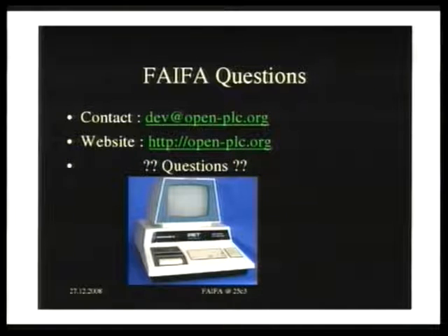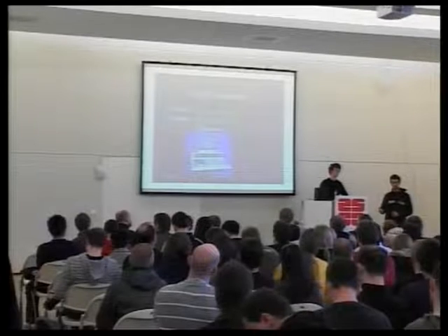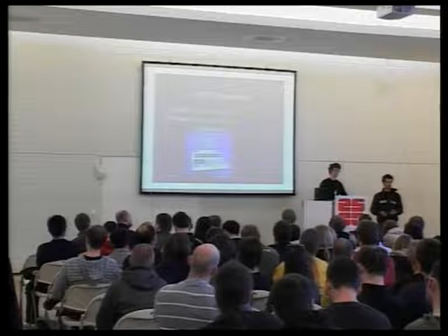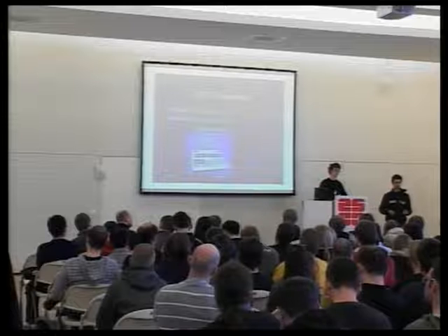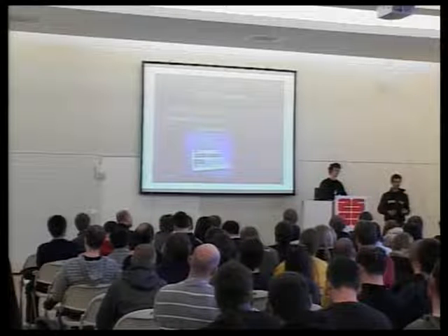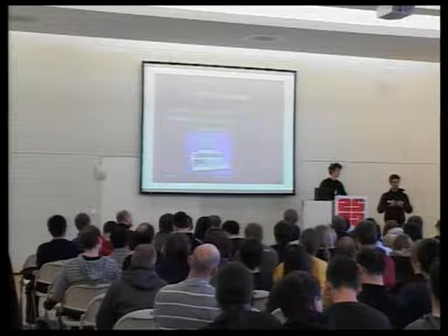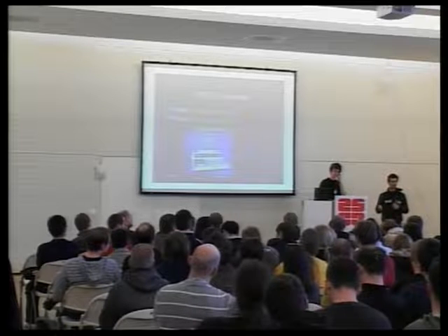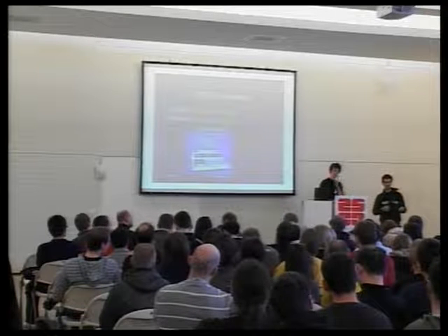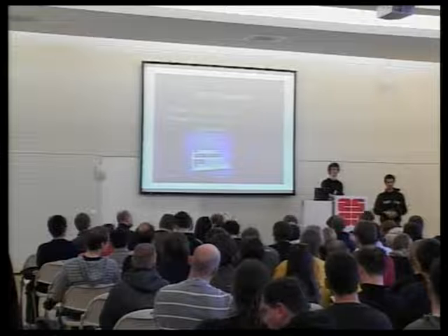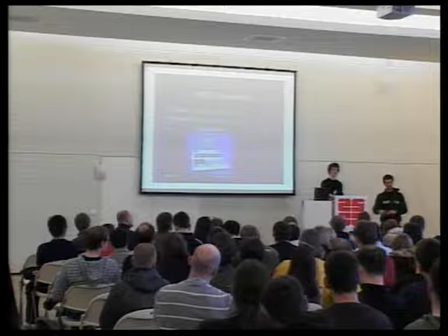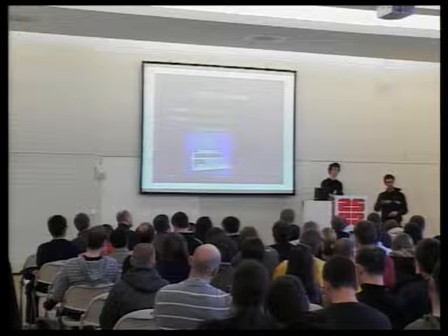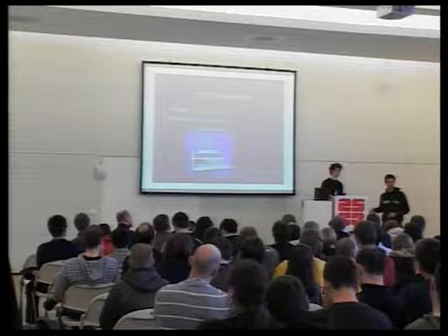In terms of technology, again, you are finding the same kind of technology. HomePlug AV, for instance, is used for outdoor also. It's slightly different because they have been implementing a small MAC layer for managing, because they want to be in master-slave mode. They don't want anybody to be at the same level on the architecture if they are an ISP. So the master is at the core of the network, and you have slaves after the meters for each home.